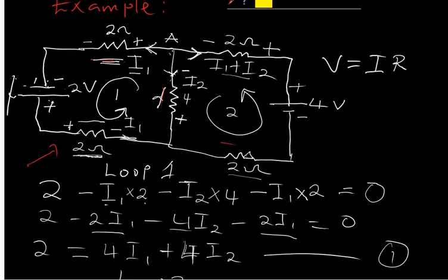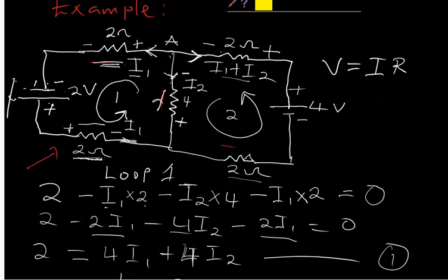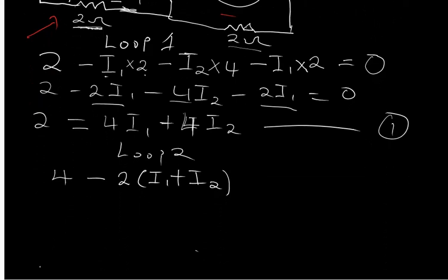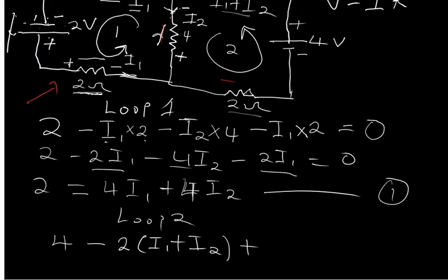Okay. So I still move, then I enter into this branch. By entering into this branch, I'm having negative to positive. This time around, negative to positive, and that's going to be a rise in potential. So that's going to be plus 4I2.